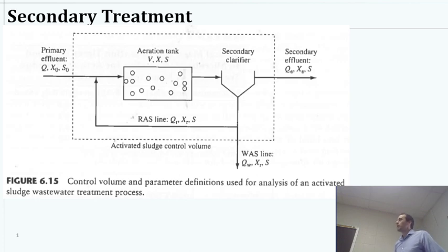So they'd use microbes, but it was a very different scenario than what we'd have with municipal situations because there was no nitrogen or phosphorus. It was all just primarily carbon type of molecules. So they actually had to fertilize their bacteria in order for the bacteria to grow, adding ammonia and phosphorus. So that's one case example there, but they had a similar system so that their bacteria could perform that task.